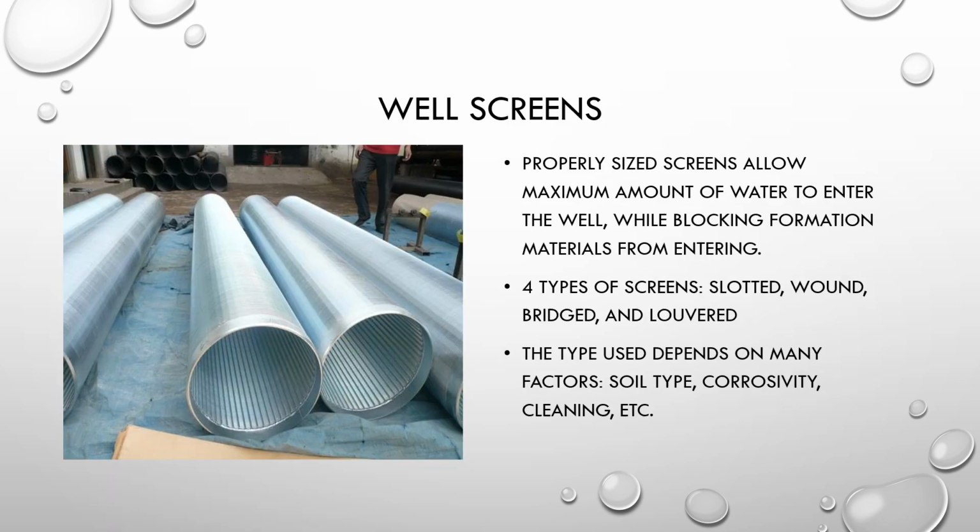Another major component of a well would be the screen. You want to make sure that these are properly sized to allow the maximum amount of water to enter the well while blocking formation materials from entering. If you get materials to enter in, it could damage your pumps, so that is quite important. There are four different types of screens. You've got slotted, wound, bridged, and louvered.